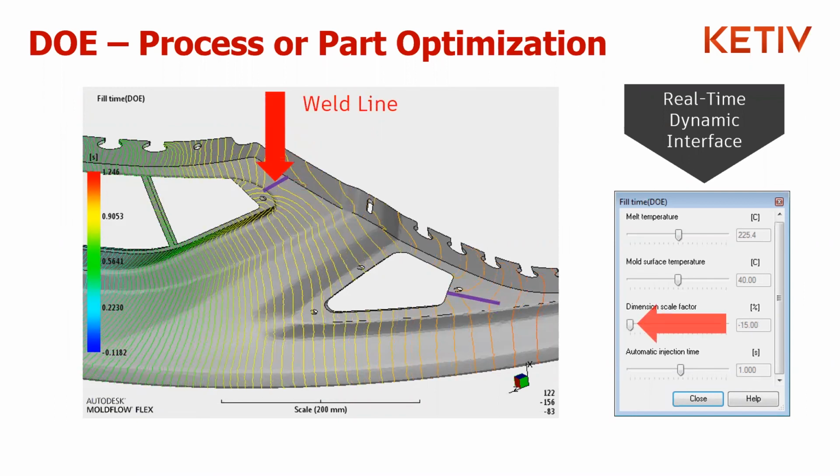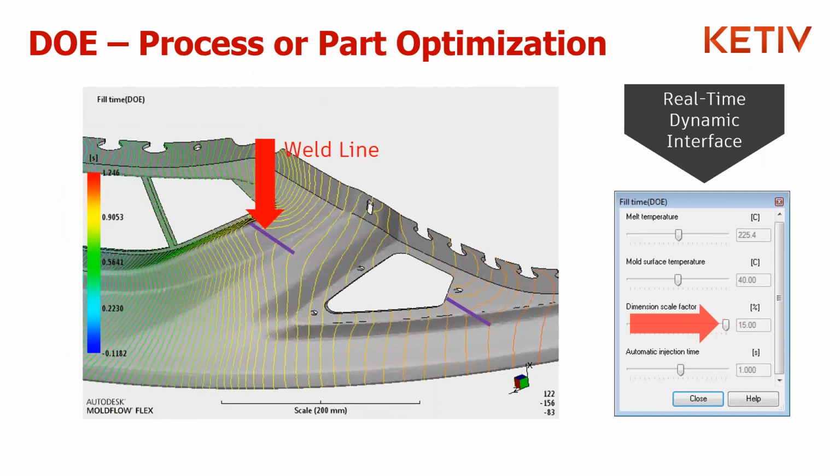Here's another game changer too, applying geometry. So in this case, the upper left-hand section is a thickness variable acting as a flow leader to drive where you want or don't want your weld line. And there's examples of that in the parametric optimization too. And one of the distinct game changers for Moldflow was having geometry now in Moldflow as a variable for these optimization routines. Very powerful. It is, absolutely.